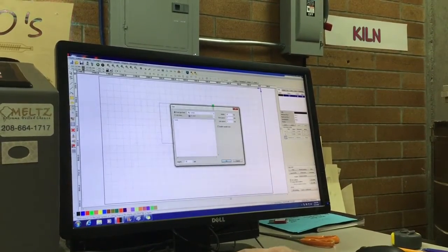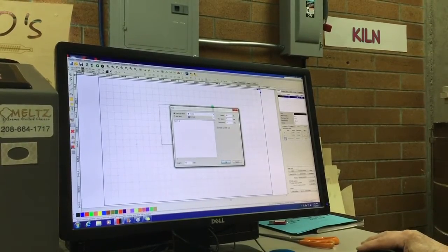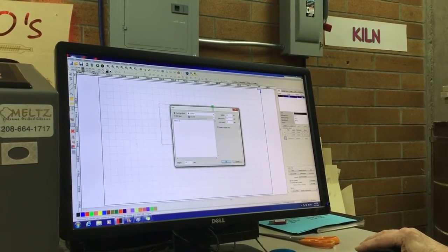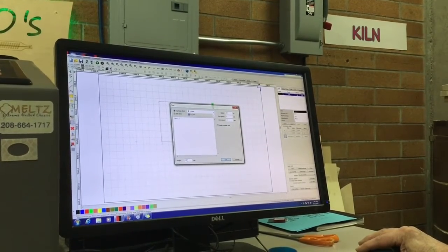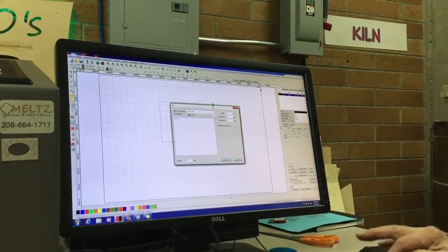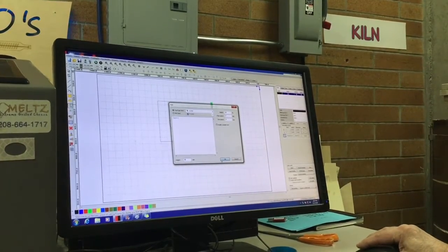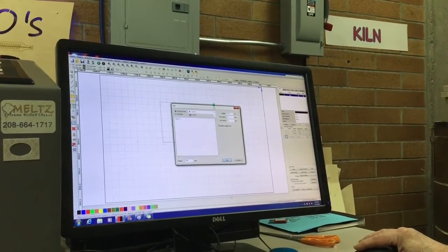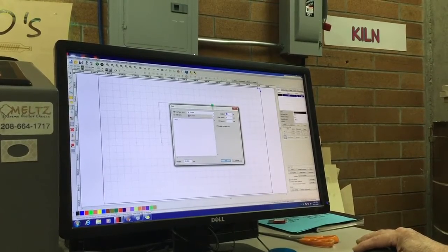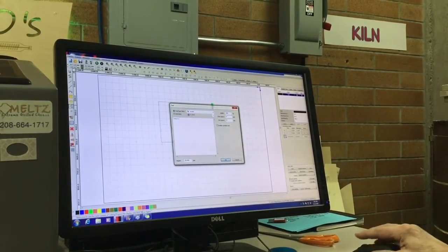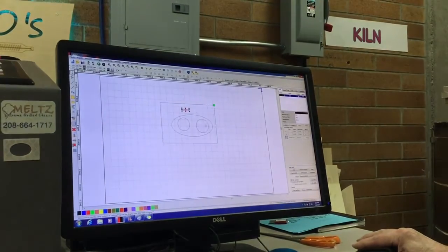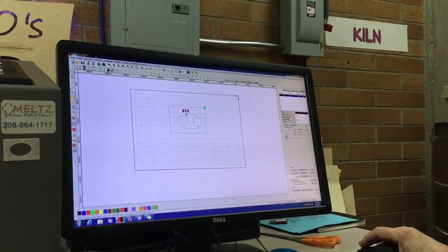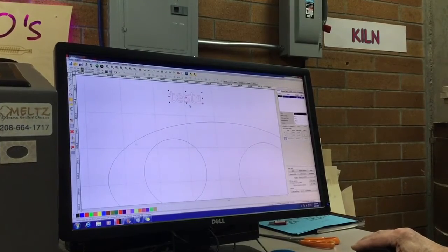Let's just say test 1. And then click. Oh, the other thing is you can specify the height here. Right now it's 35 millimeters. Let's make it 20 millimeters. You can specify the width as a percentage of height. So 100% width would be full width. And that's a normal looking text. Let's zoom in on that.